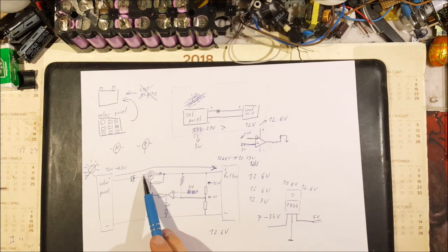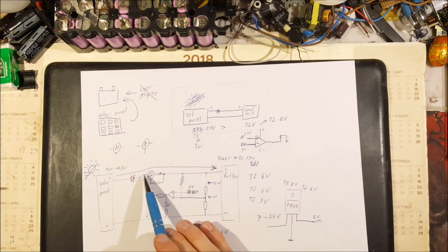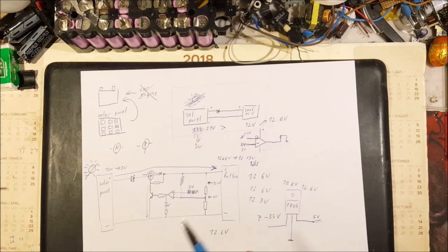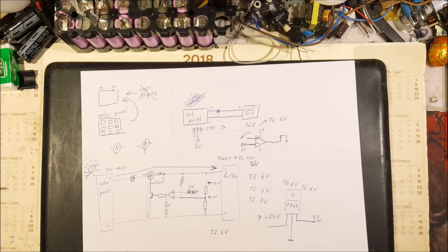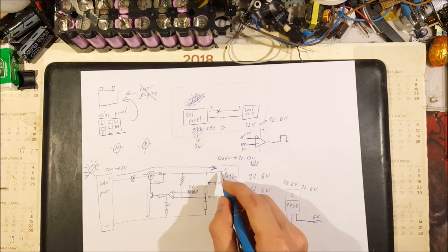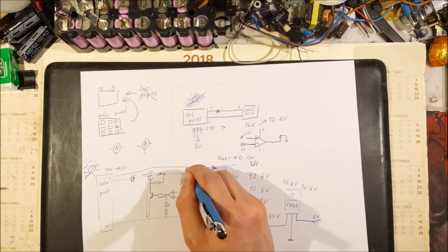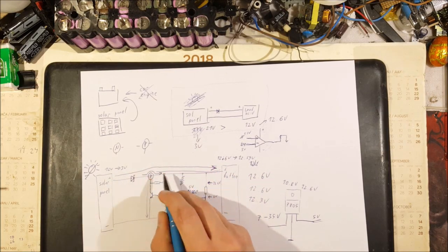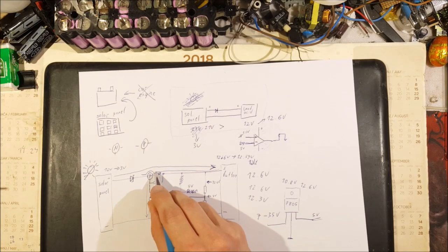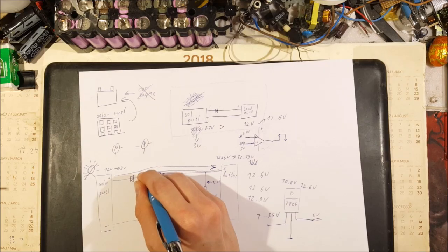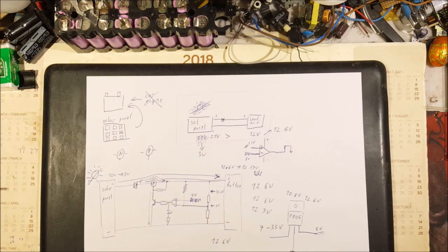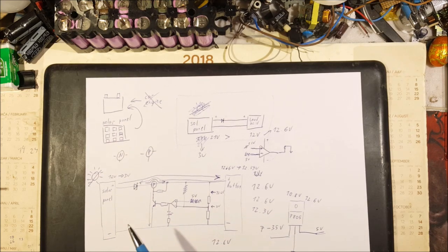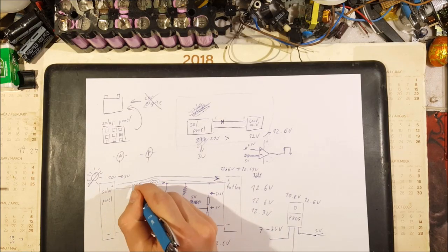Yes, this MOSFET is closed, meaning that it does allow current to flow from this side to this side and also from this side to this side, but there is this little diode right here, meaning that the power from the positive of our battery will go all the way to our MOSFET, pass straight through our closed MOSFET and hit this diode, and it can't go further because this little diode is allowing the current to flow only in this direction.